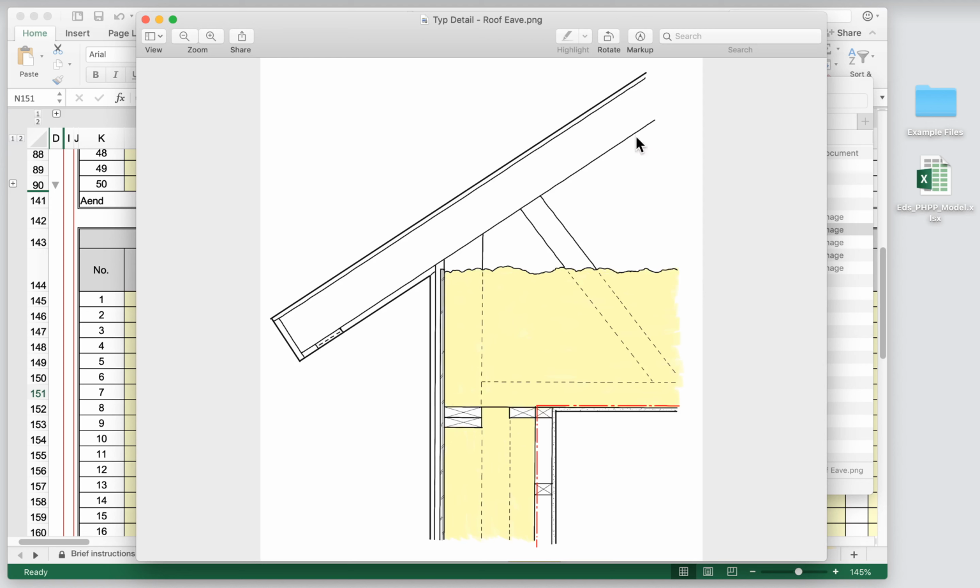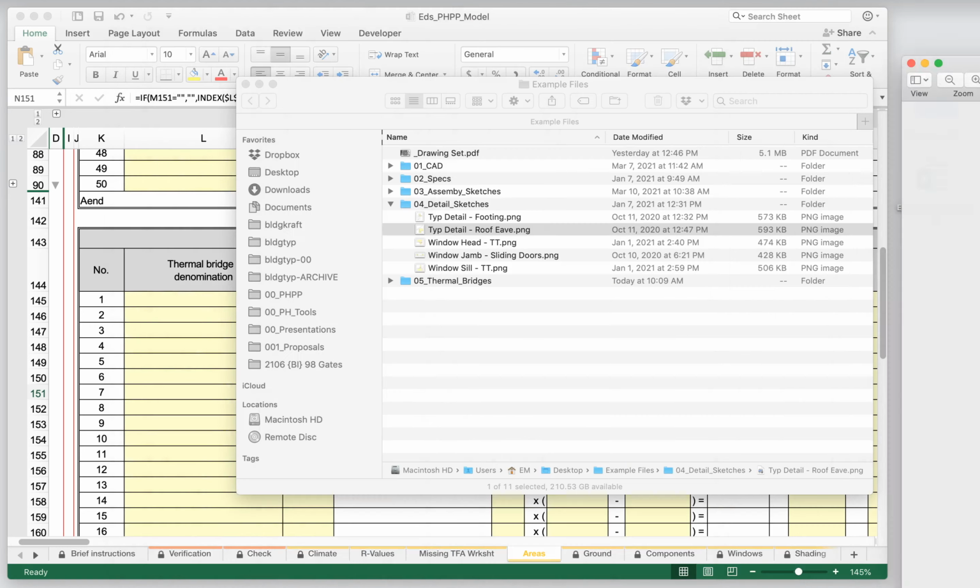In a typical truss where this upper rafter element was sort of down here, you'd have a constriction in your insulation assembly as you move to that outside corner. So these raised heel energy trusses are great for getting full continuity of insulation all the way around. Okay, so this is the proposal for our eave detail. So we have those two proposed details, an eave and a floor assembly there.